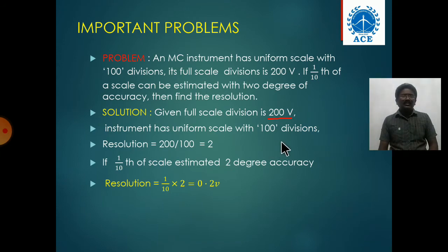Every system will give some errors. Generally here you can identify 3 types of errors. One is the random error, one is the gross error. Gross errors are human mistakes, and the other one is systematic errors. Systematic errors you can identify in 2 ways: instrumental errors and environmental errors.